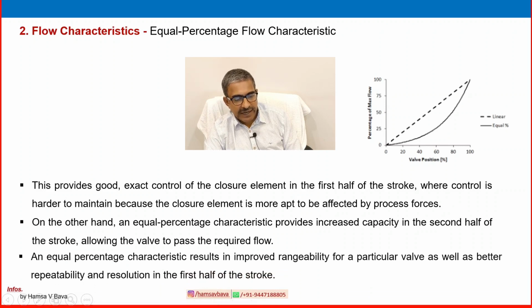An equal percentage characteristic results in improved rangeability for a particular valve, as well as better repeatability and resolution in the first half of the stroke. These are the advantages of equal percentage flow characteristic.